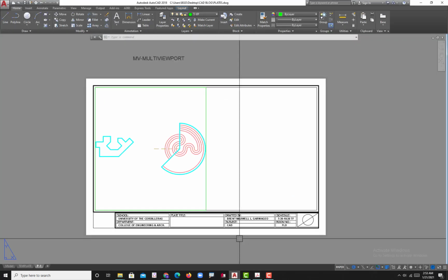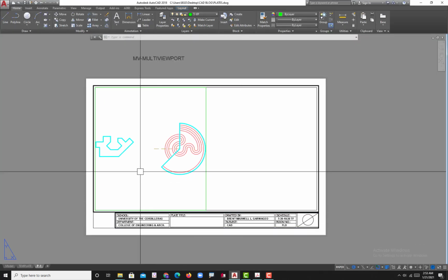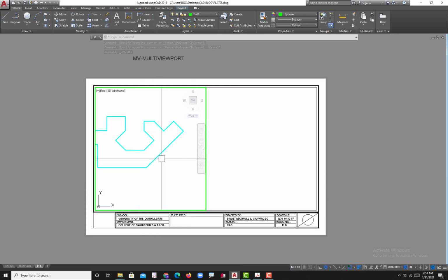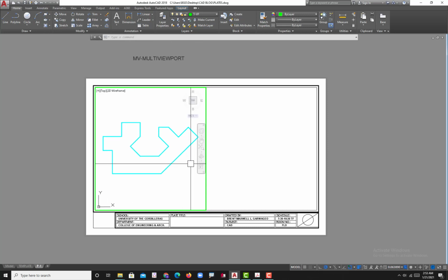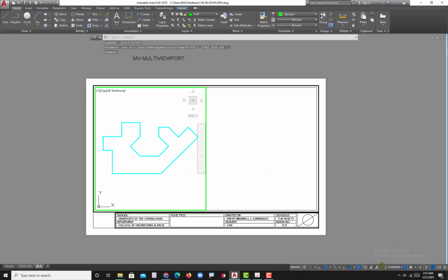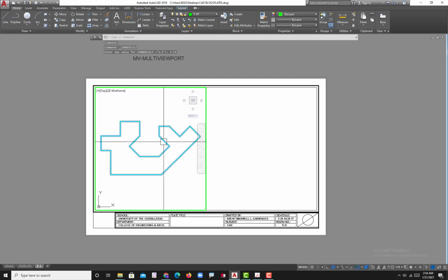So let's go with CAD. Double click inside, and then just magnify first, and then go to the scaling, the scale of the selected viewport, and find 1:15. If it's not here, you go with custom, and then you add 1:15, where 1 paper unit is to 15 drawing units. So hit OK, and I hope that is already there. Select that one. Okay, so it is now arranged.